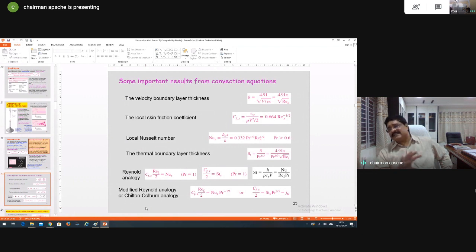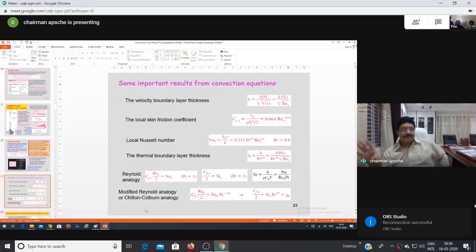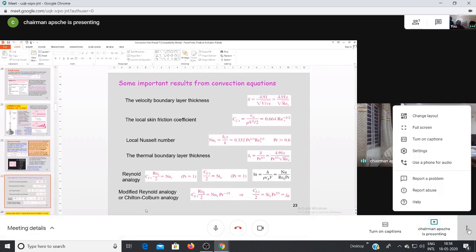So these are the 7 parameters that we normally talk about: rho, L, mu, k, h, Cp, V. These are 7 parameters. All of them, one or other, use all the 4 fundamental units, because L has length unit, rho has density with mass unit kg, and thermal conductivity and heat transfer coefficient have temperature parameter. So h, Cp, V, of course, what happens when each one of them varies. But as a group, straight away look at it.